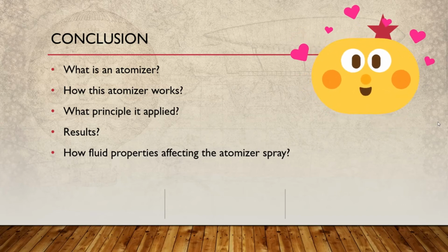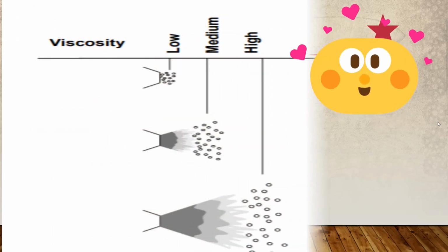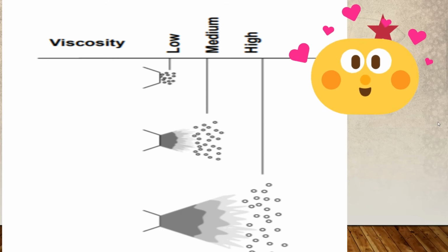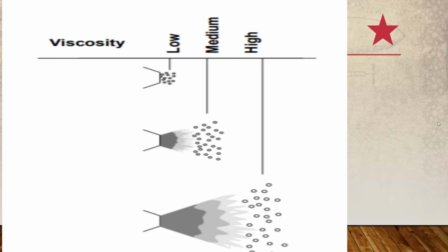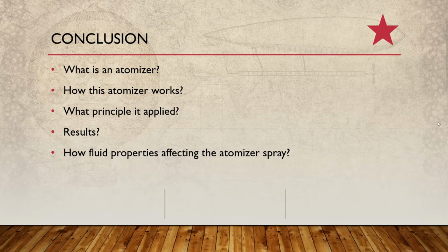Surface tension tends to stabilize a fluid, preventing it from breaking up into smaller droplets. Everything else being equal, fluids with higher surface tensions tend to have a larger average droplet size upon atomization. A fluid's viscosity has a similar effect on droplet size as surface tension. Viscosity causes the fluid to resist agitation, tending to prevent it from breaking up and leading to a larger average droplet size. Density causes a fluid to resist acceleration, similar to surface tension and viscosity. Higher density tends to result in a larger average droplet size.